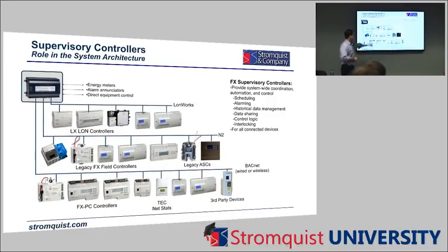All right, so your Jace is responsible for all of this stuff. Scheduling, it's going to write a schedule for all of these controllers to follow. Now we can have several different schedules. We're not set up where we just have our 8 to 5, open and closed type scenario. We can have a schedule that says, here's our holiday schedule.